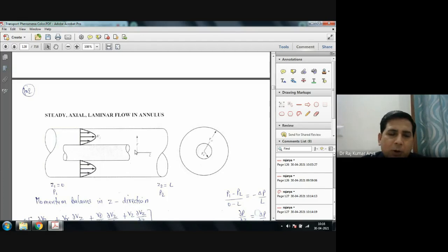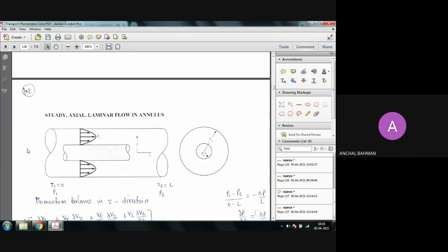So they always pass hot water or steam inside this, and outside of that you have the flow. The same thing also happens in your double pipe heat exchangers. You may have a hot fluid or cold fluid inside the tube, and outside of that you have a different fluid flowing with a different velocity. And you are also interested in how this velocity variation would happen, because it will impact your heat transfer or mass transfer process, correct? Yes, sir.